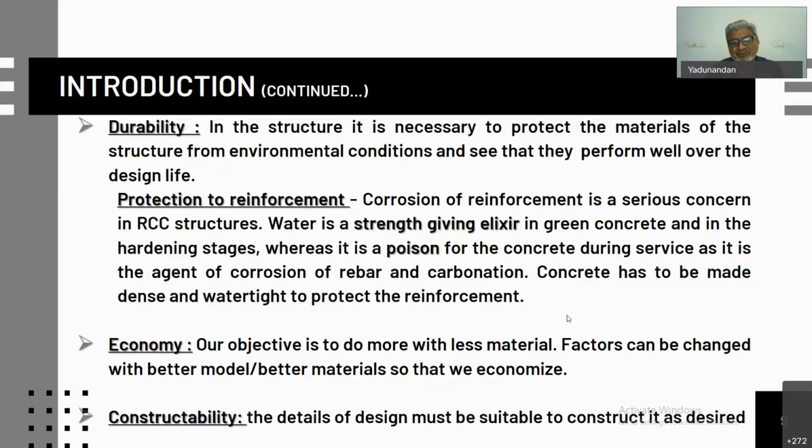But the very reason for moving from working stress method to this was that we were not utilizing the strength of these materials to the maximum possible extent because we did not know much about their behavior. We were assuming they were linear, elastic, and trying to contain the so-called stresses by assuming a linear behavior to a certain value. But based on laboratory observations today, it is possible for us to construct a situation of failure where the complete section has resisted the load and the maximum strains have been reached, and corresponding to this maximum strain reaching condition, we are trying to find out the force and stresses corresponding to that condition.